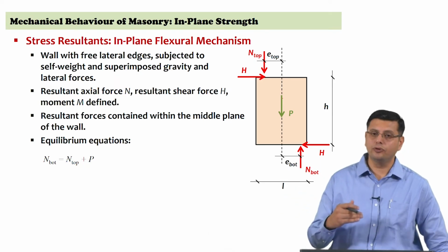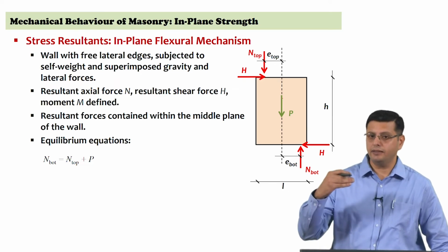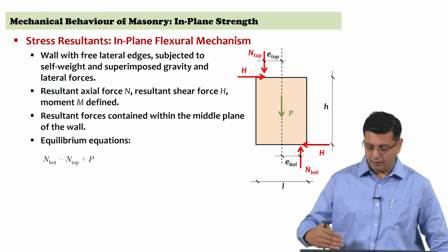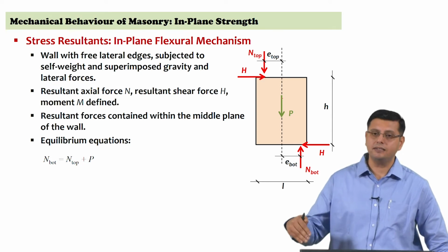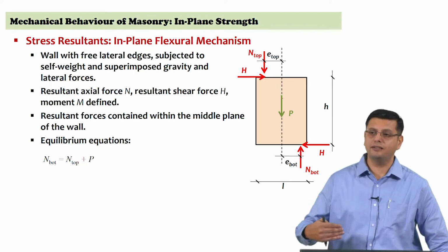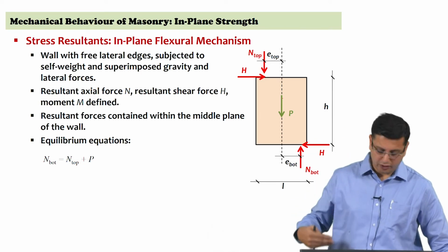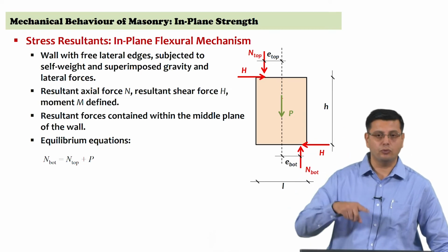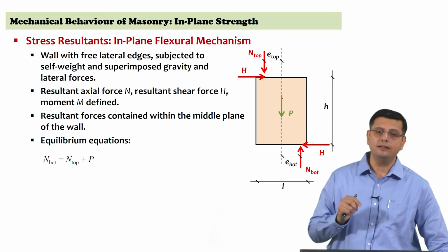Therefore, it is important for you to be careful where you are making the estimates of the stress. If you are making the estimates of the stress distribution in the wall at the mid height, then be careful about the contribution of the self weight that is being considered. If you are at the top, there is no contribution of the self weight. If you are at the bottom, you have a full contribution of the self weight of the wall. So, you will have to be careful in what plane you are making the calculations.